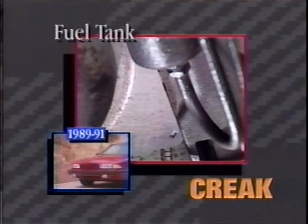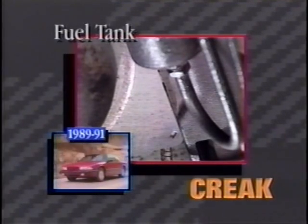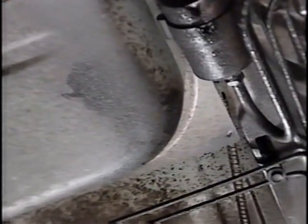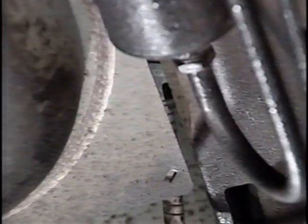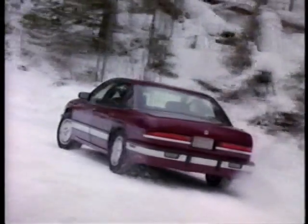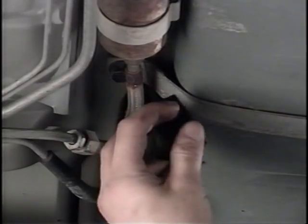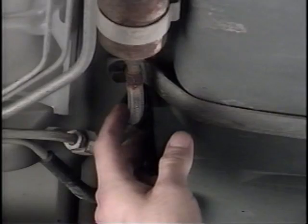In another fuel tank related condition on some 1989 through 91 cars, a creak or groan noise may be caused by the front flange of the fuel tank contacting the rear underbody crossbar. This contact is most likely to occur during a twisting motion, such as when the car is turning up a steep incline. Depending on the build date of the car, this condition may be repaired by replacing the fuel tank support straps, or by installing new straps and strap spacers.